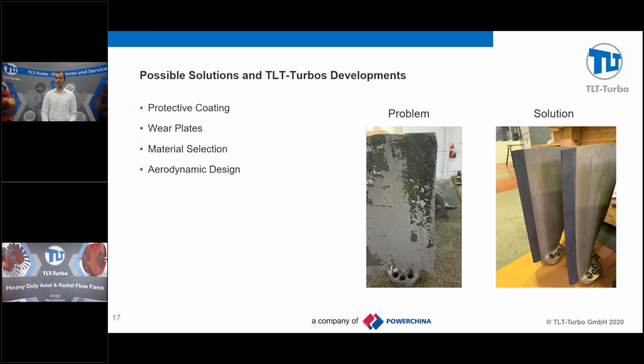So what are now possible solutions and what are TLT-Turbo's developments? You can see one case here, which is from a Canadian mine. They have a combination of rock dust, of a very low pH value for corrosion, and also water droplet impingement. And they had aluminum blades with a tungsten coating on it, and the tungsten coating was flying off because the corrosion was destroying the bond between the tungsten and the aluminum.